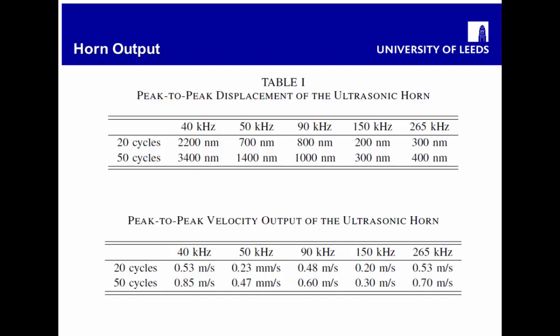I showed you an equation before. The force is related with the displacement. So what I need is a high displacement. But this is a trade-off you always get. If you increase the frequency, or even choose another transducer, you will start getting lower displacement values. So this is a trade-off which I cannot do anything about.